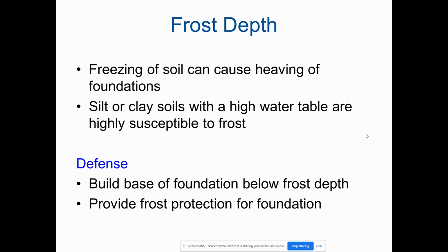Okay, frost depth. Freezing of soil can cause heaving of foundations. Silt or clay soils with high water tables are highly susceptible to frost. Build the base of the foundation below the frost depth, and provide frost protection for the foundation.